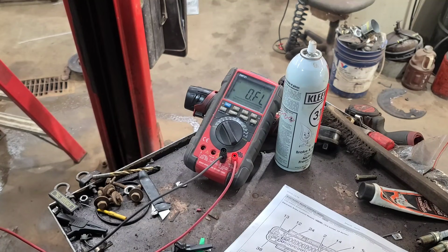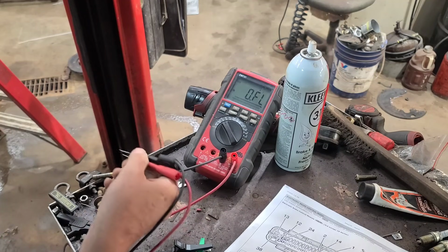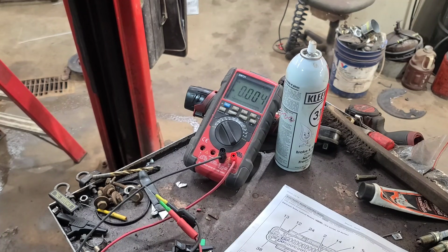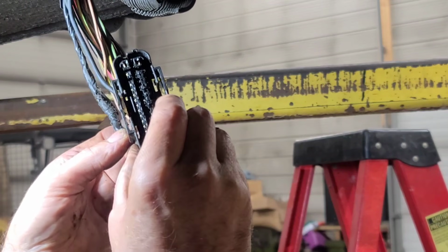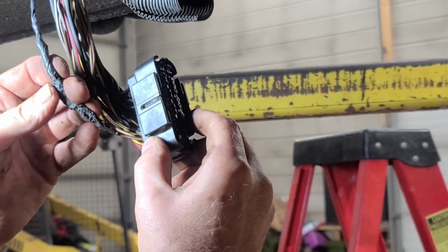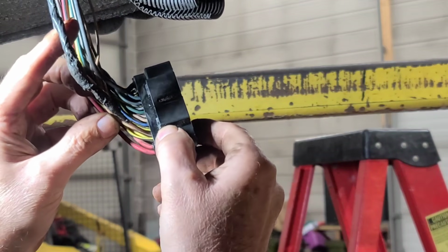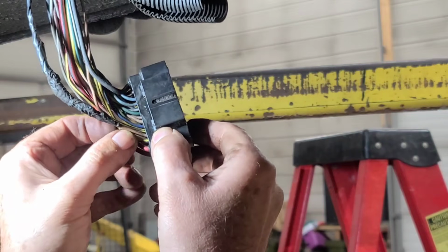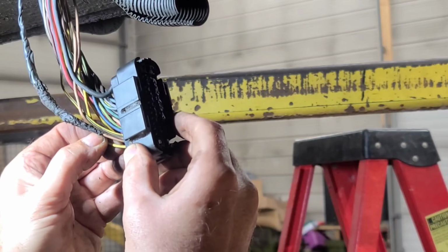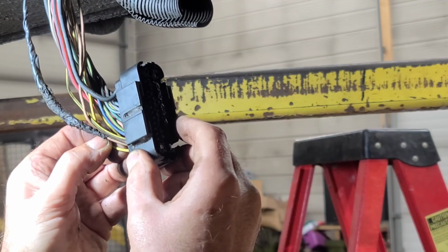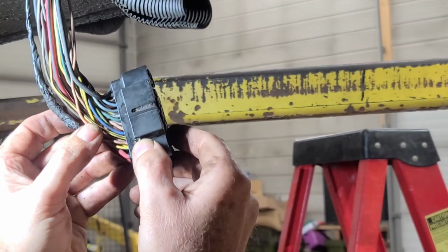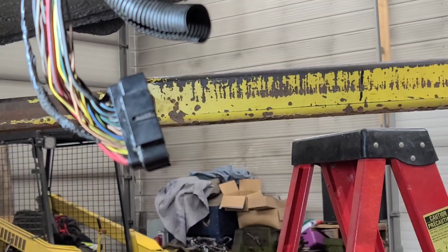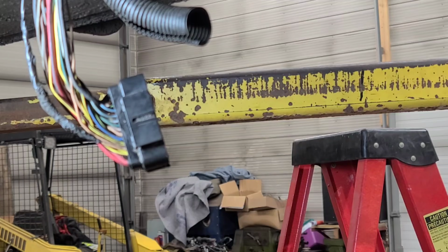I'm gonna pop this plastic piece out of here. Well, this doesn't make sense. Pin 23 is definitely a CAN bus wire and it's been fixed. But pin 24 is not a tan wire, it's yellow. So maybe this is the wrong brake application. I gotta look for another pin out, but these pins don't match.